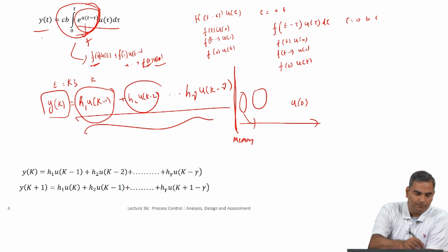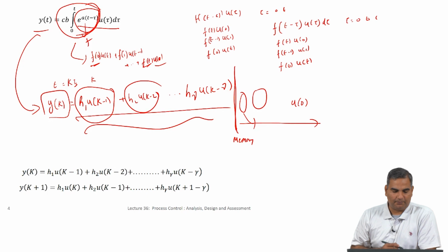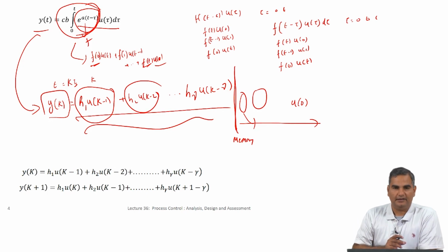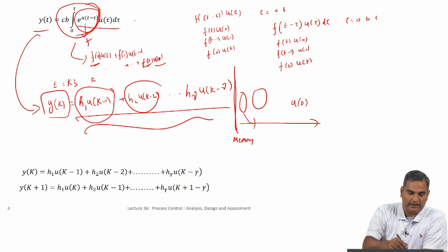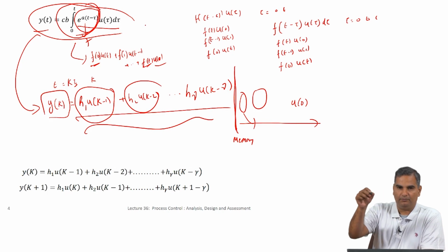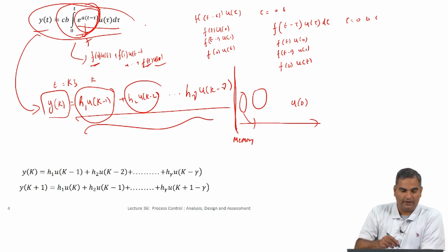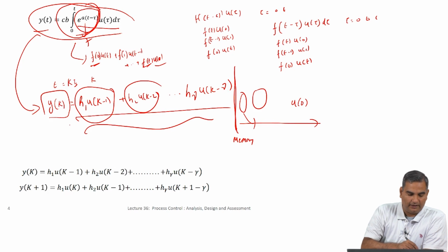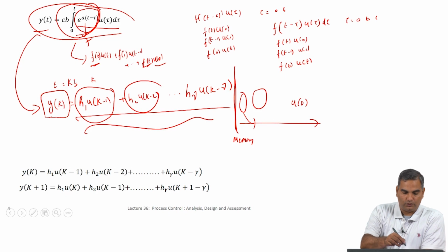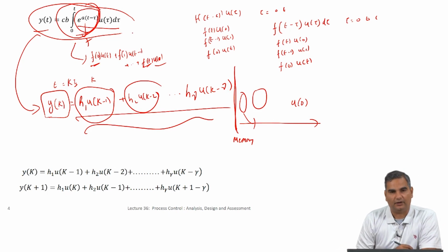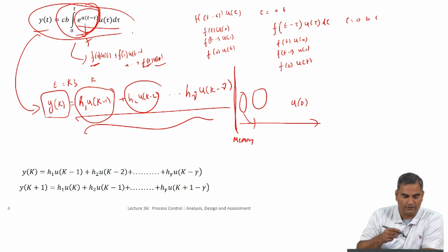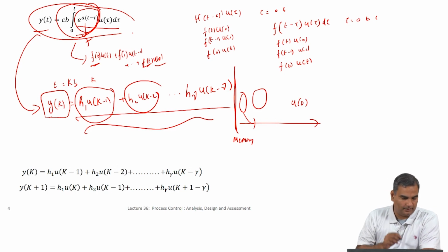But before that, I just do not want you to think that we have done some hand waving and gone from an integration to summation. Actually, under certain conditions and under certain assumptions, you can show that even if you integrate this equation with continuous u, where the u is changed in a stepwise fashion, and then you actually do this integration, and then actually compute yk at those time samples, you can show that this and this will be exactly the same under certain conditions. Okay.